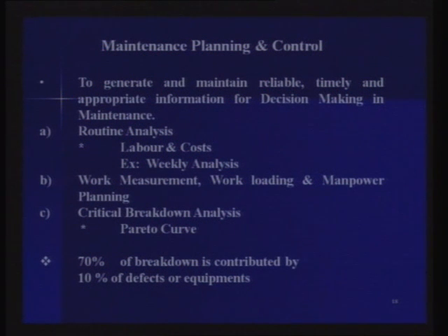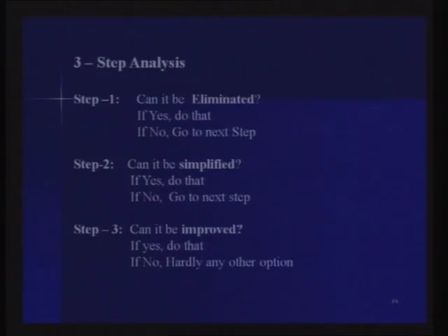The whole purpose is to categorize, to classify the defects, by how frequently one defect occurs. So the defects that occur frequently should be taken care of first. We have 3 steps for this. Step 1, whether it can be eliminated.